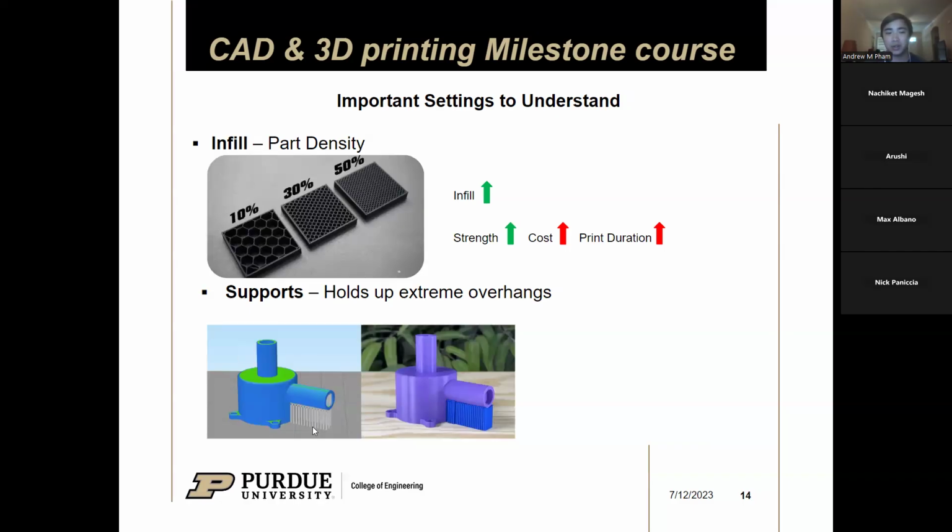So you can see in this photo, there are these kind of gray lines here, and that is support material to make sure this part gets supported so the print finishes correctly. As a designer, if you're designing for manufacturing, at least for me, I try my best to make sure that I don't need to have supports in my models, right?